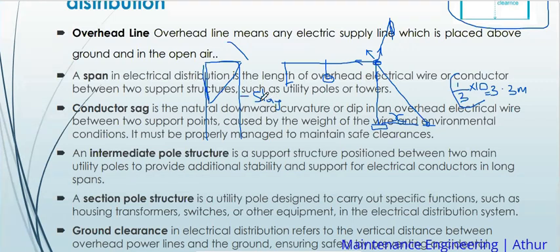This stay would have come this side from the pole up to here because of the standard distance for it. But because this person doesn't want much of his area to be covered up, we use what we call an outrigger bracket and we use an outrigger stay. And therefore, the stay just remains near the pole. But it still protects the pole at the same rate as the normal stay.